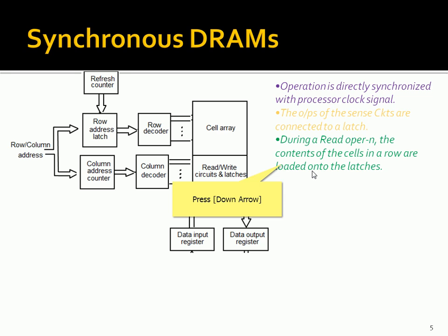We have discussed at length the basic dynamic random access cell, which contains a transistor and a capacitor. Even with no power, the capacitor tries to conduct some power with the help of residual charge. That will be maintained for a certain amount of time. After that it will stop, and stopping means we may lose the data. In other words, to avoid losing data, we need to give some power. How can we give that power? By refreshing. So there will be a refresh counter.